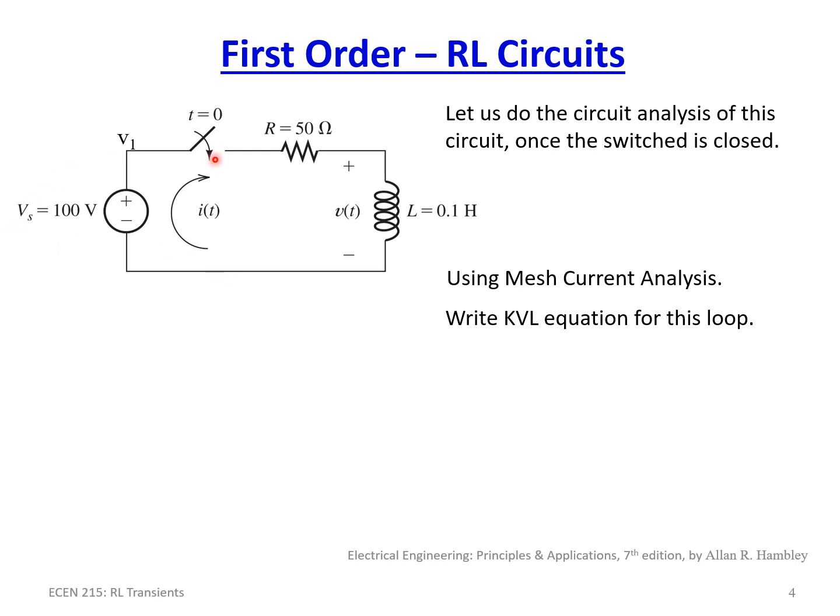What Kirchhoff's voltage law says is this loop must equal 0, all the voltages added together, starting here with the voltage across the resistor, the voltage across the inductor, and then the voltage coming in the negative terminal, subtracting Vs, must equal 0. So let's go ahead and write those values. R times I of t plus VL of t, the voltage across the inductor, whatever that is, minus Vs. This is our governing equation for this circuit. That must be followed.